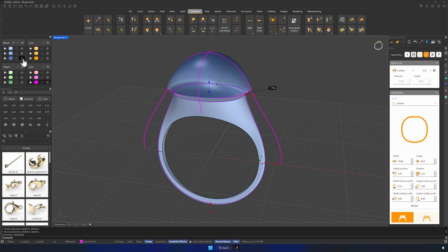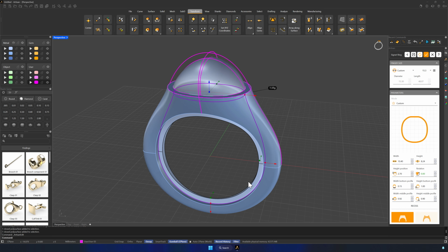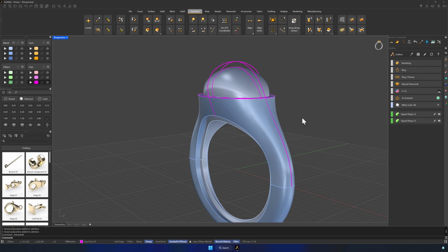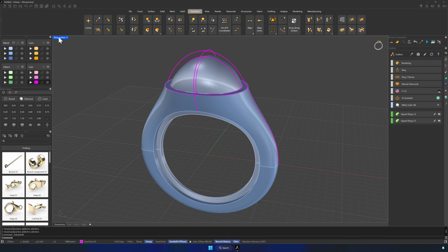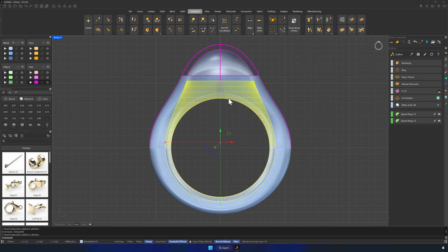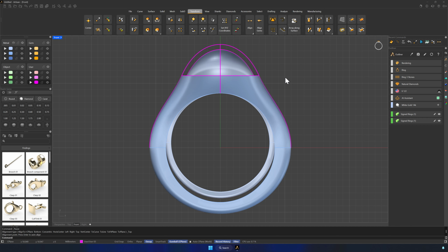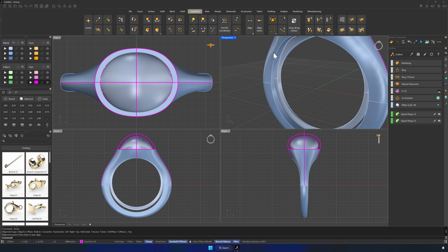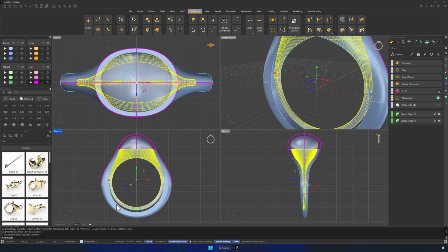Now you can show the other shank to see how much material we will hollow out, although we still need to position the inner shank. Accept the command. From the front view, select the inner shank, and inside the Align button select Align Top. Position the inner shank at the same height as the outer shank. We will show all views again. As you can see, we will only hollow out part of the shank, avoiding the bottom part. This way we achieve a smooth hollowing.